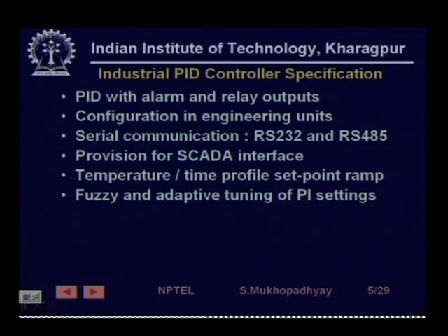Fuzzy means there is a special technique called fuzzy set theory, which is used to design controllers. So, you can have fuzzy and adaptive tuning. Adaptive tuning means that the controller continuously keeps adapting as the plant changes. So, you could choose one of these to get the PID settings.